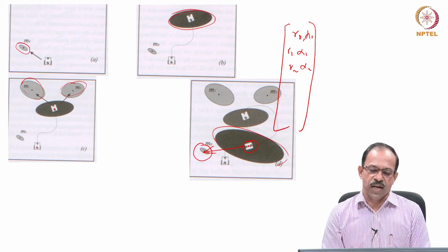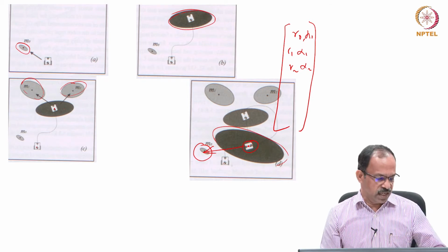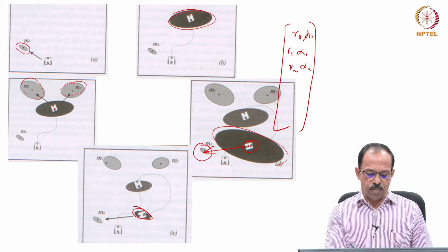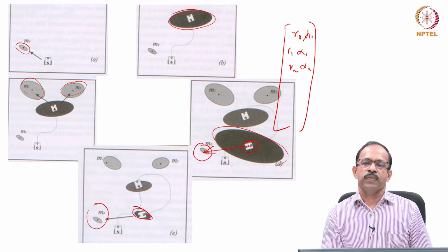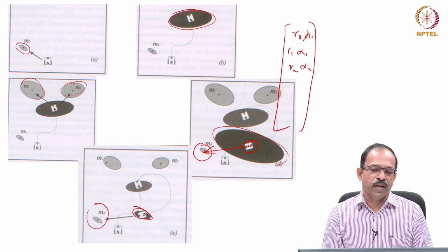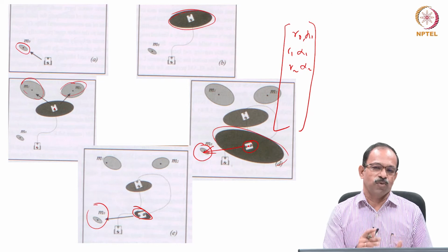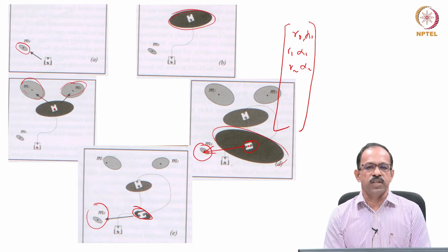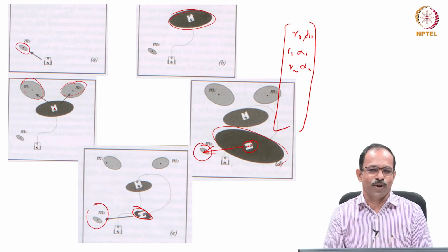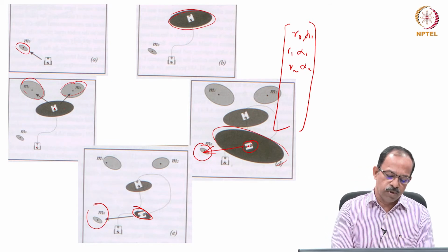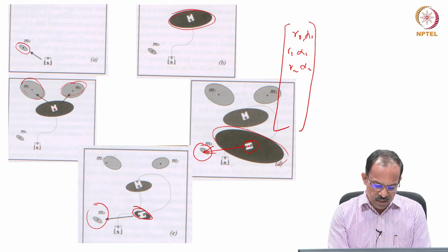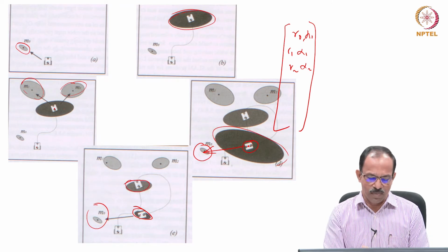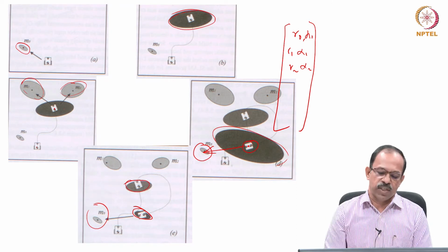And once it does that, the position uncertainty will come down drastically. This uncertainty has come down because it has seen the same object, or the same feature, and since it's already there in the database, the robot will be able to use that information, fuse these two pieces of information, and then recalculate its position. Similar to the Kalman filter localization we saw, it will be able to recalculate. And once it recalculates this position, it will back calculate and find out the uncertainty in this one also. So similarly, it will be able to recalculate this position.